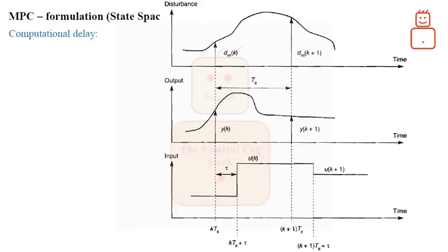Let tau be the time taken by the MPC to predict the control action sequence. The first item in this sequence is u of k. The input signal u of k is assumed to be held constant until it is recomputed Ts time units later. This sequence is repeated at time (k plus 1) multiplied by Ts, and regularly therefore. So, one can notice a time delay of tau between the sampling of the process states and injection of the computed control action.